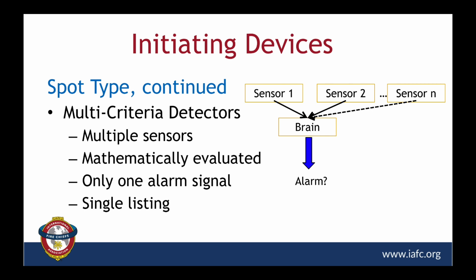The microprocessor also will utilize filters to eliminate common nuisance sources. Now, this detection process only takes a couple seconds to either confirm that it is a true fire or to conclude that it isn't a true fire, thereby eliminating an unwanted alarm.